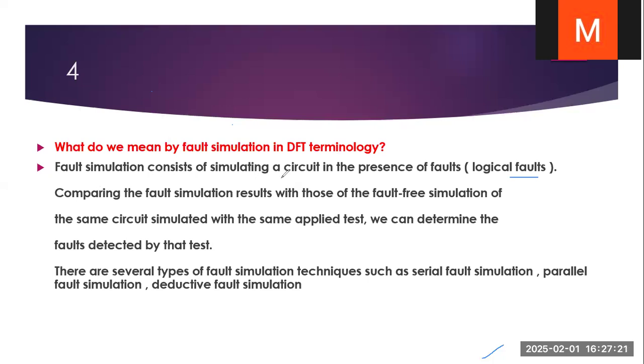Fault simulation consists of simulating a circuit in the presence of logical faults. Comparing the fault simulation results with the fault-free simulation of the same circuit simulated with the same applied test, we can determine the faults detected by that test. There are several types of fault simulation techniques such as serial fault simulation, parallel fault simulation, and deductive fault simulation.